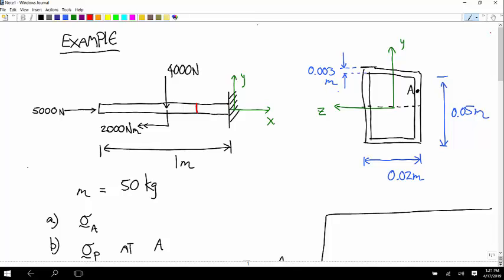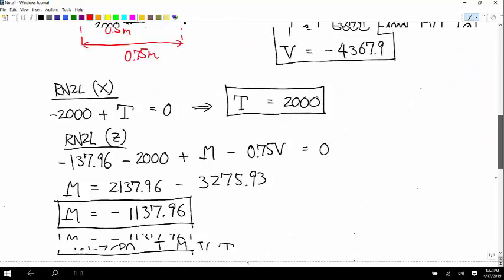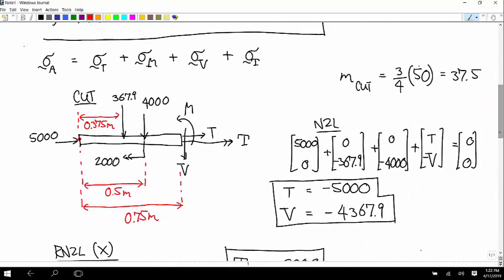Well, the neutral axis is where there's no stress due to bending moment anyway. So you'd still be able to do this in that case. Same thing with shear. If it doesn't meet the shear requirement, but you're at the top or the bottom, you can still do it because the stress due to the shear force would be 0.